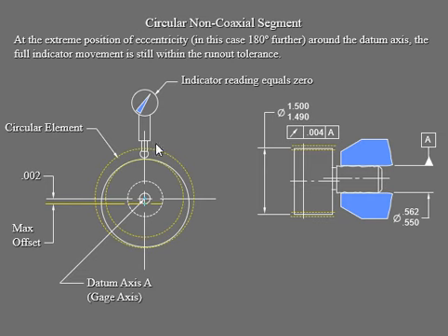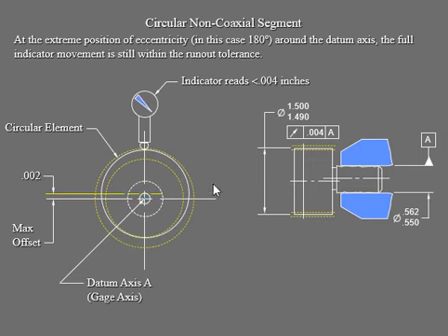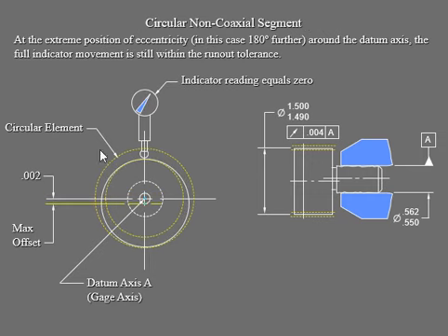All right, then we are now going to go straight into it, and now it is reading 0. See how it is different from the first example, where it was showing you the max, but less than 0.004, and now it goes down. Your indicator reading is going to show you 0. See how sensitive these verification devices are. The best ones are, of course, expensive to buy. A regular one is not that expensive, but your accuracy is kind of off.